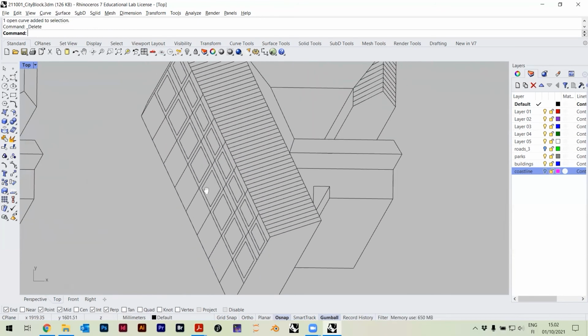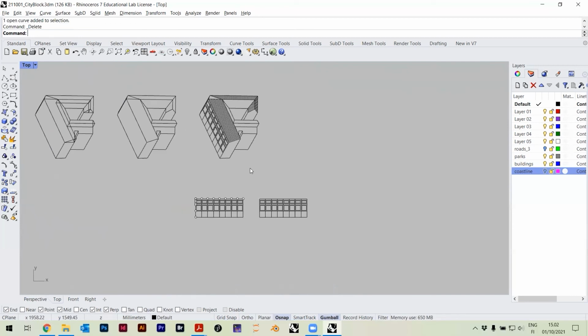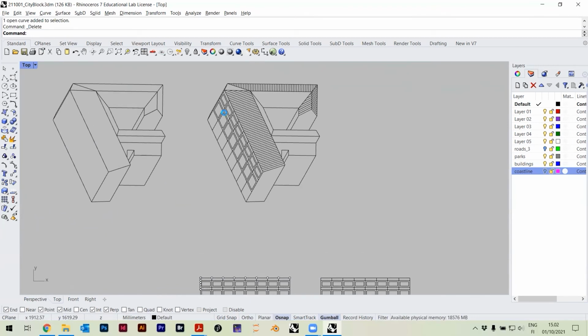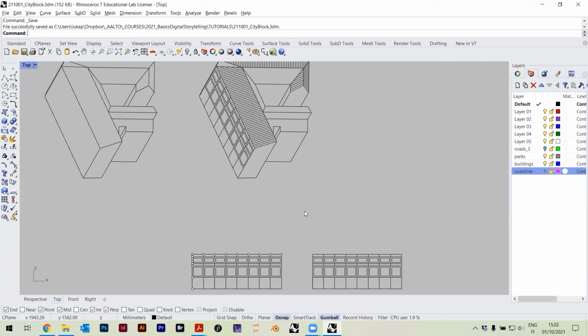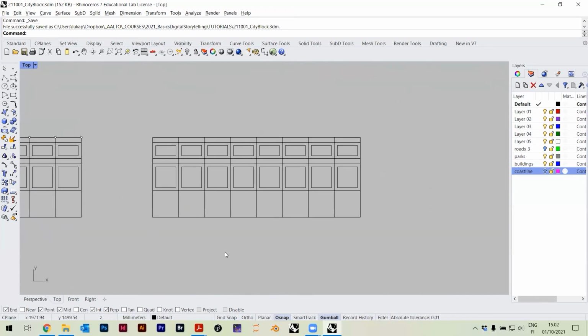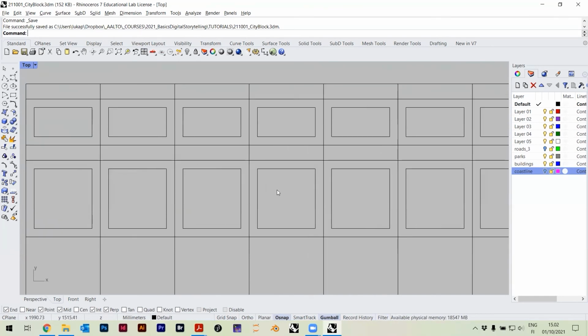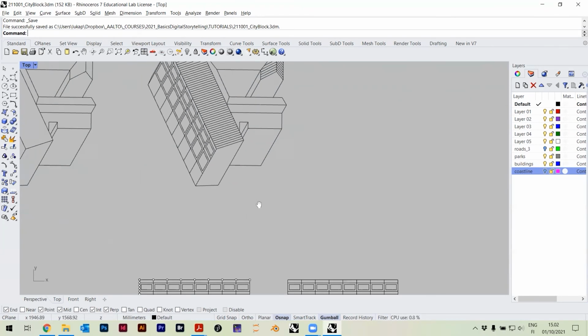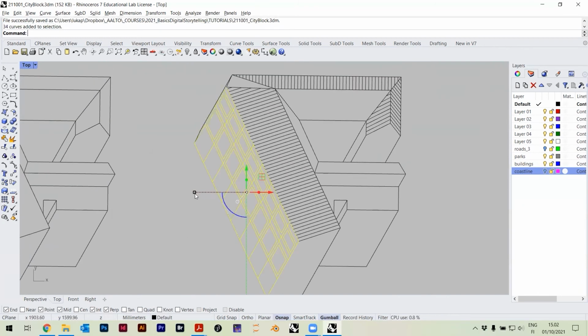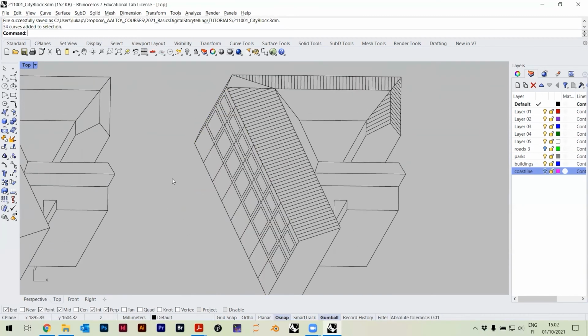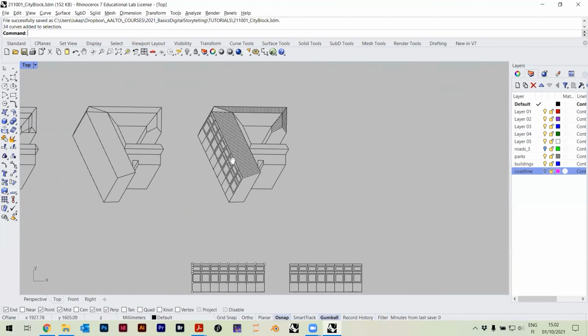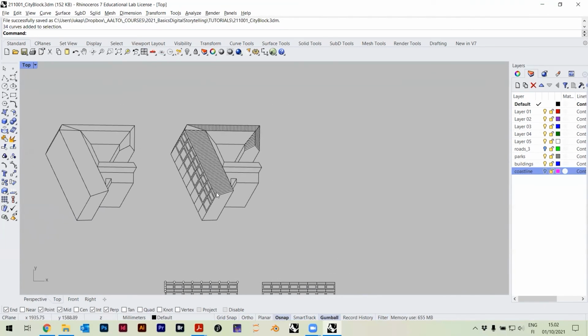So basically when you're drawing these, you should always try to draw facades in this view, because it's just easier, as most facades are orthogonal, windows are rectangles and so on. You can quickly copy things around, you can also start adding details here and so on. But then basically we just use this method to glue it, or project it in its correct position back on the facade.